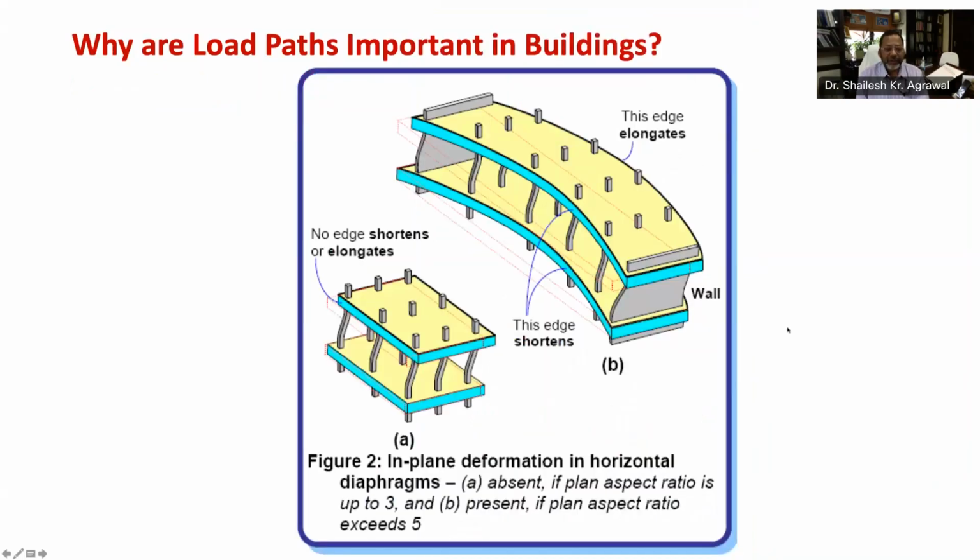First, floor and roof slabs, also known as horizontal diaphragms. They are thin, wide structural elements laid in a horizontal plane at different levels. These transfer inertia forces induced by their own masses to vertical elements on which they rest. During earthquake shaking, these horizontal diaphragms act like beams in their own horizontal plane and transmit inertia forces to vertical elements such as structural walls and planar frames.